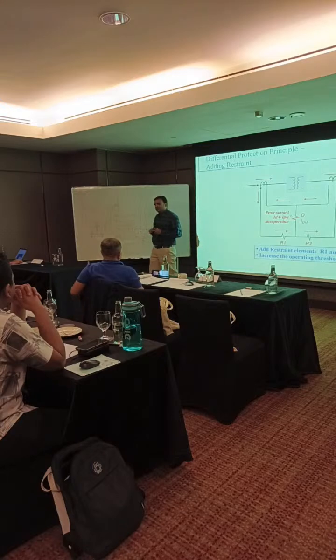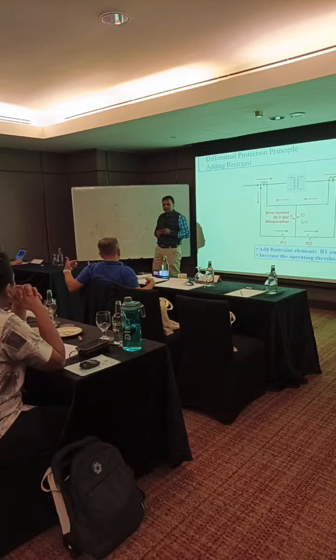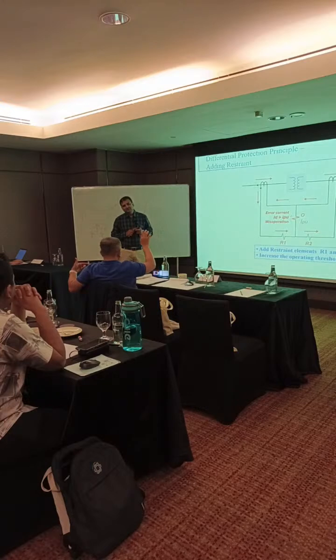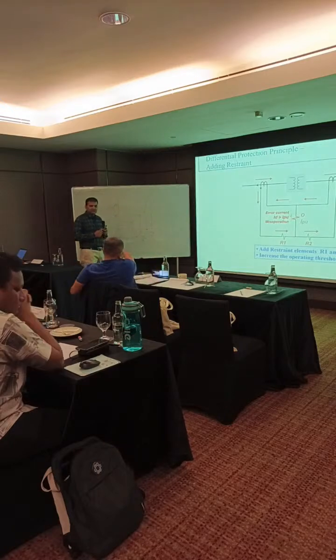You inject current on side one and side two. You increase one side, and you go to the digital display and search for IDIF and IR. Then do another test, calculated by this formula.